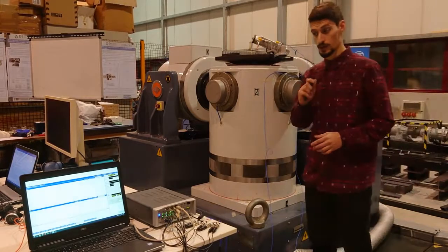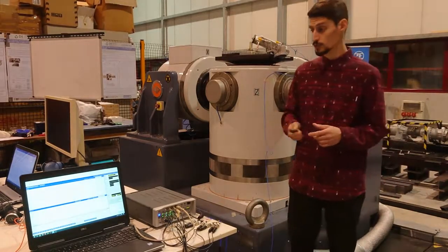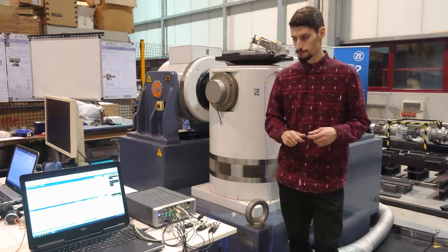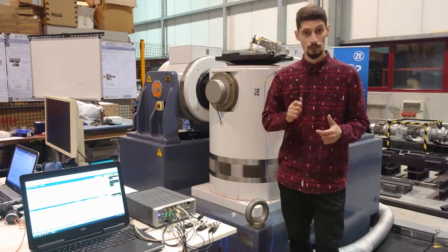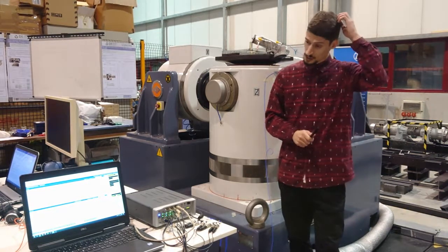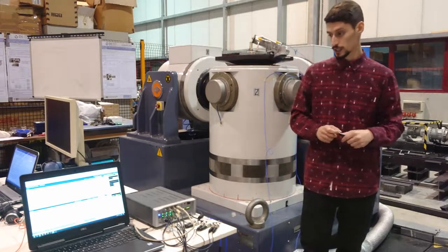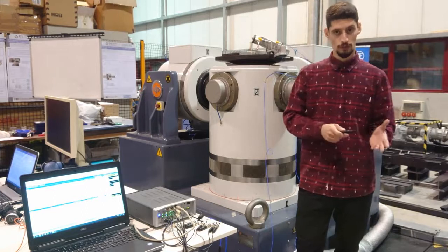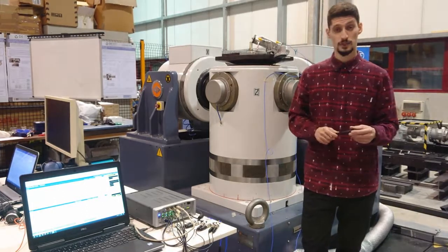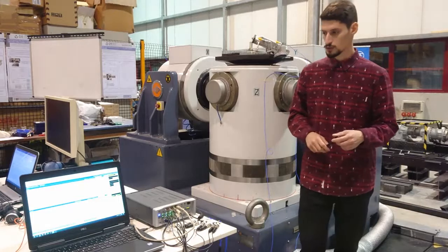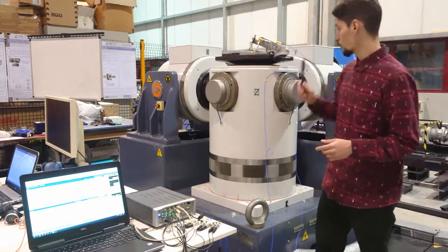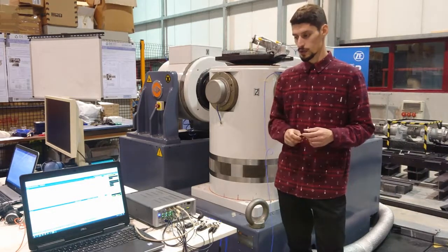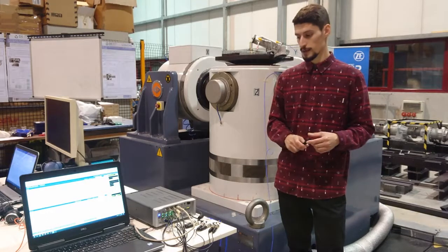So now I switch on the shaker and I'm going to go to the computer just to show you how to perform a vibration control test. We will start with MIMO random, then we will skip to the TWR control technique. We will perform the same vibration control test. Of course, with MIMO random, we will define the test specifications in frequency domain, so the PSD and the TSD of our control accelerometer. Instead, in the TWR, we will define the test specification directly in time domain.